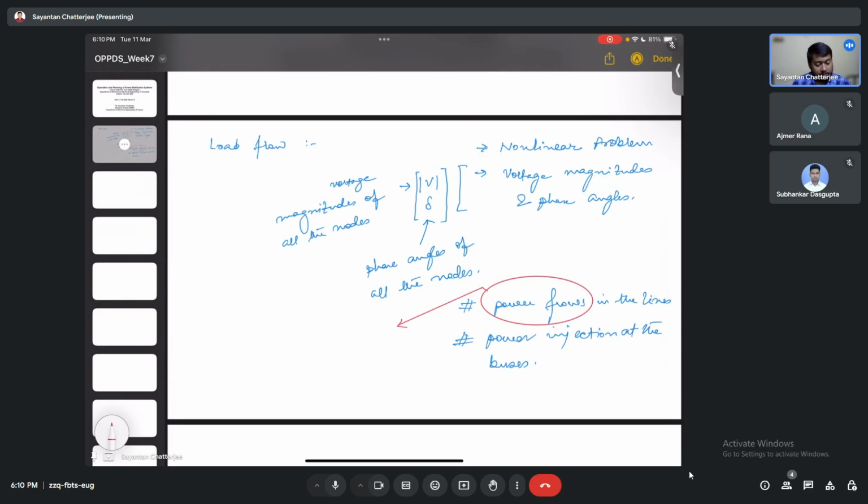But the need of finding these power flows is that power is getting transferred from one area to another, from the substation to the load centers, to the distribution side feeders and laterals, flowing towards the customer mostly. Now in the DER integrated scenario power can be bidirectional, but mostly over the entire day, the power flows from the substation to the customer end.